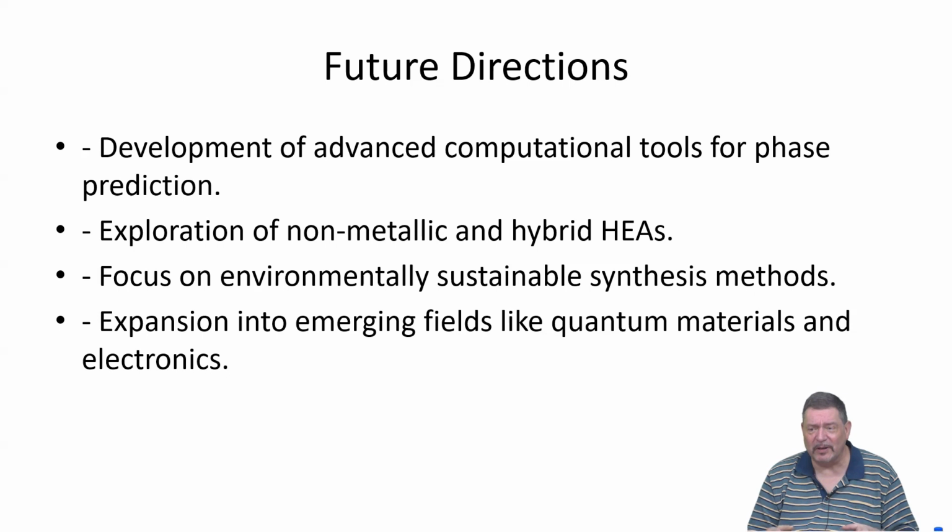And this is why experimental work is still very much valid. Or you couple CALPHAD to density functional theory, DFT. There, again, we put 50 atoms together, right? And then on an ab initio basis, the DFT calculation can predict lattice stabilities of phases which we don't yet know about. It will just try every combination, and maybe comes up with this strange phase I just mentioned as a solution, maybe showing that in this compositional range, it has the lowest free enthalpy.